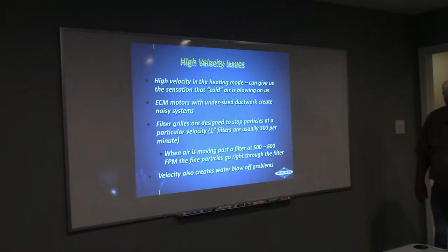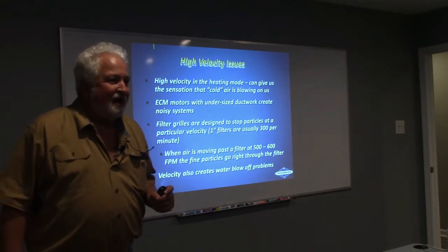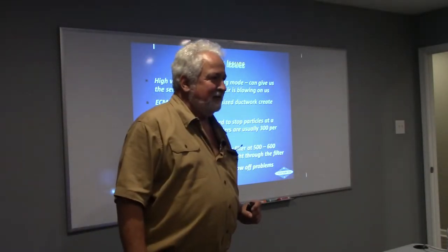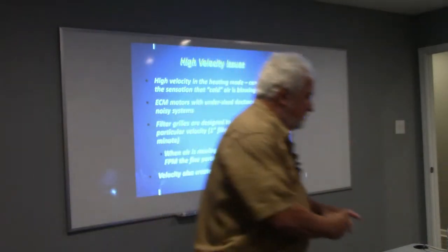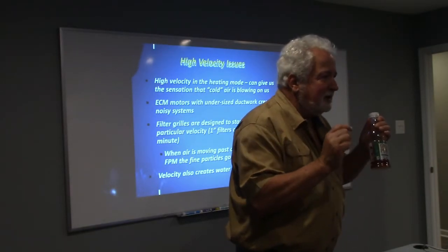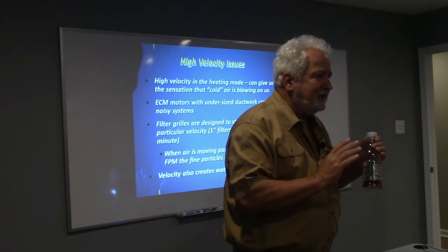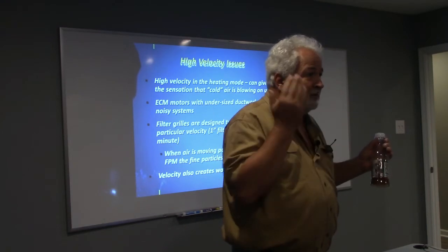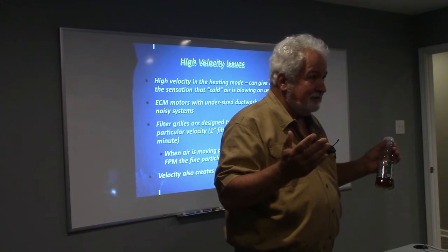Oh yeah, you got it. It's going across that coil like that now. How much time was it able to stay in? It didn't have any time, did it? If I didn't have any time to lower the temperature, do you think it stayed in contact with that coil long enough for it to be able to start to condense? If it didn't have any time to stay in. So what happened to dehumidification? Gone. What happened to the cooling? Gone. You seeing this?